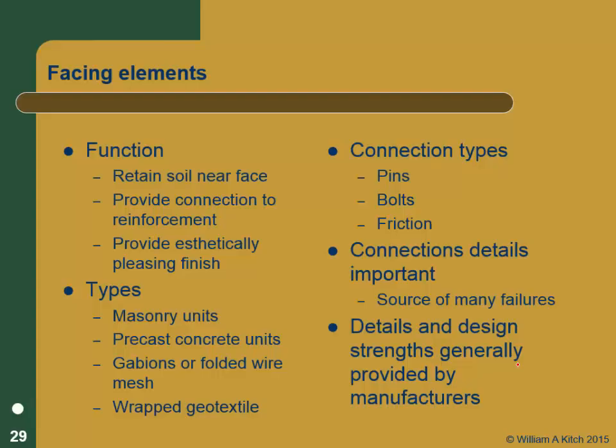Questions? Yeah, Jack. The connection between the facing and the reinforcement. Reinforced Earth is a proprietary term for these T-panels with the little strips behind them. We've seen pictures of them. They had problems with their connections in some of their early designs, and corrosion at the connections, and that's where they failed. So now you've got a facing unit that has nothing holding it. The facing unit falls out. Now the wall starts eroding behind the facing unit.